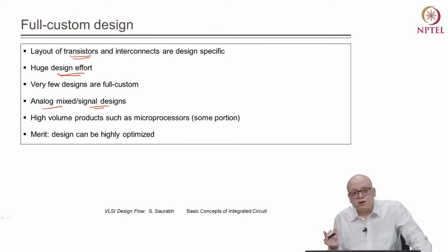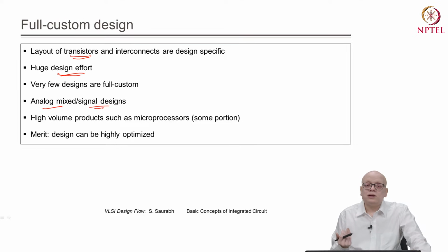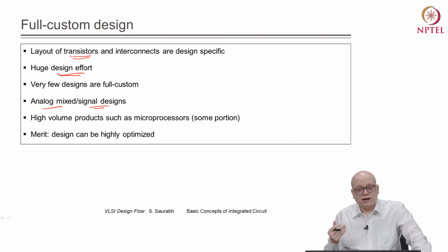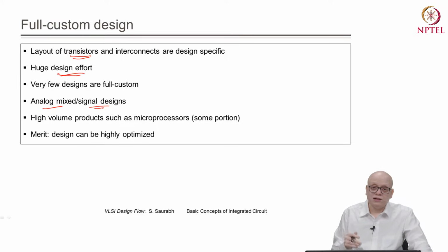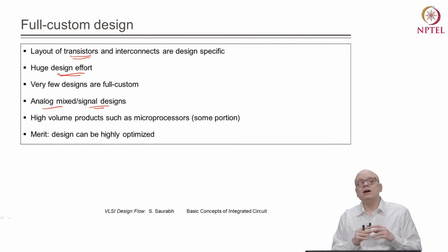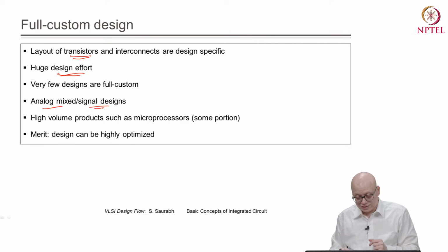And what are the merits of full custom design? The merit is, of course, the optimization, right? We are designing at the transistor level, therefore as a designer we have a lot of flexibility in a full custom design, and if we have that flexibility, we can utilize it to improve the quality of our design, and as such the quality of full custom design can be much better than other types of design styles.